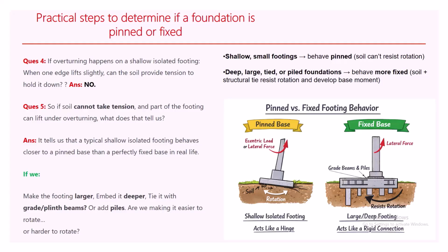So as you can see, shallow or small footings behave like a pin support, and providing beams makes them behave fixed, just like what we have explained.